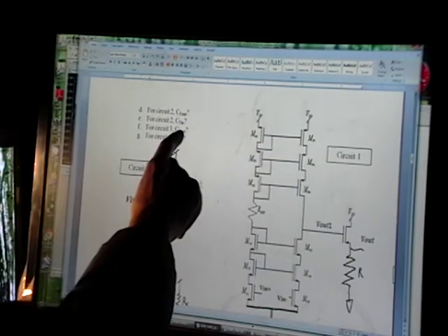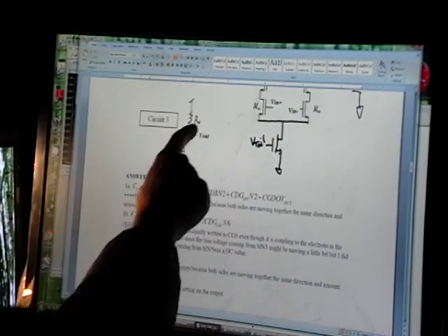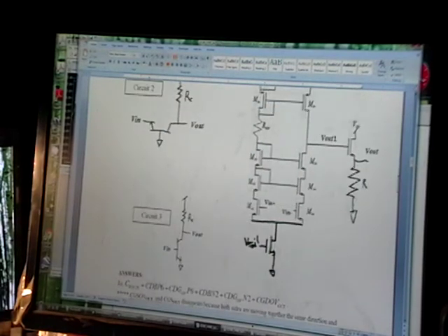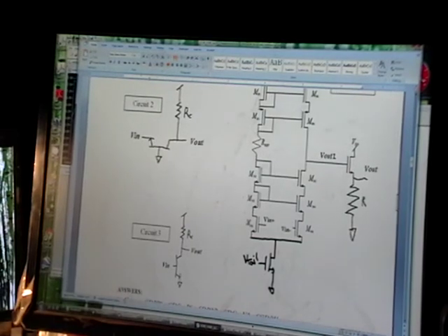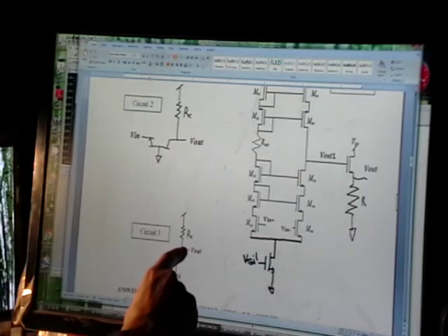1F. Okay, V out of circuit 3. So here's circuit 3 and asking about V out. And we actually already did that problem. Nothing different from the common base right here. You're sitting on the collector, so you see the collector-substrate, which is to ground, and you see the collector-base.